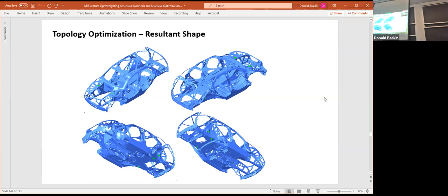But you have to see the danger in this, because there are all kinds of different loading conditions. And if you choose the wrong one, maybe the car's going to be great with rear impact, but with front impact, you've got a big problem. It doesn't protect anybody. You have to be very careful about how you choose loading conditions, right? How they represent real life the best.